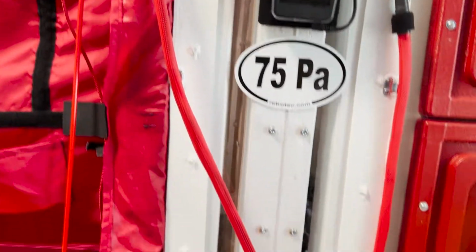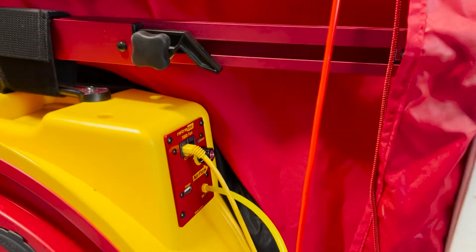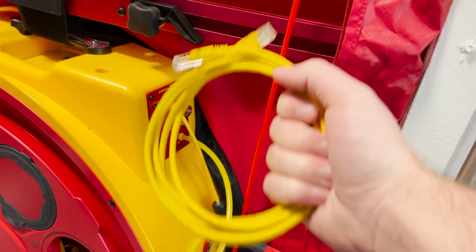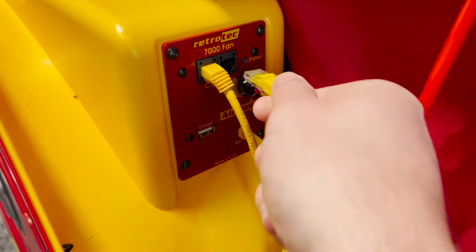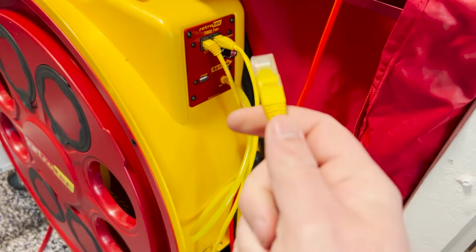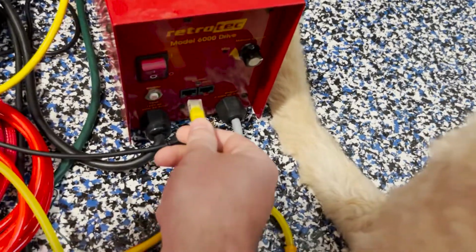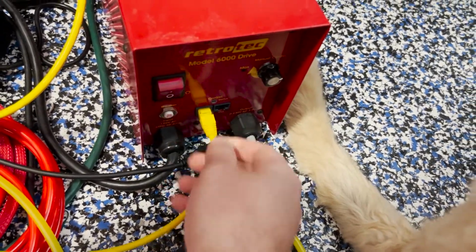So in this scenario, we'll do what we call daisy chaining the fans together. The first fan on the line will have a Cat5 cable coming in from the top of the first DM32, and then we'll use the out port on the fan to connect another Cat5 cable going into the in port of the next fan. So when you hear someone saying daisy chaining the fans together, that's what we're doing. We're setting up the fans for a common control setup.